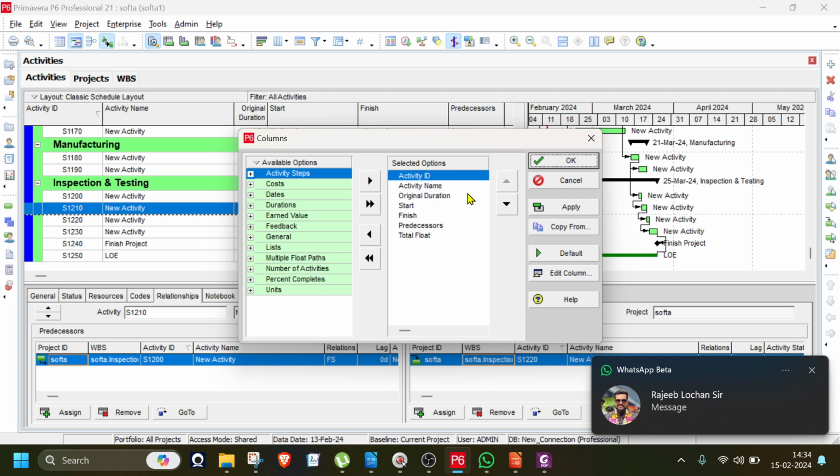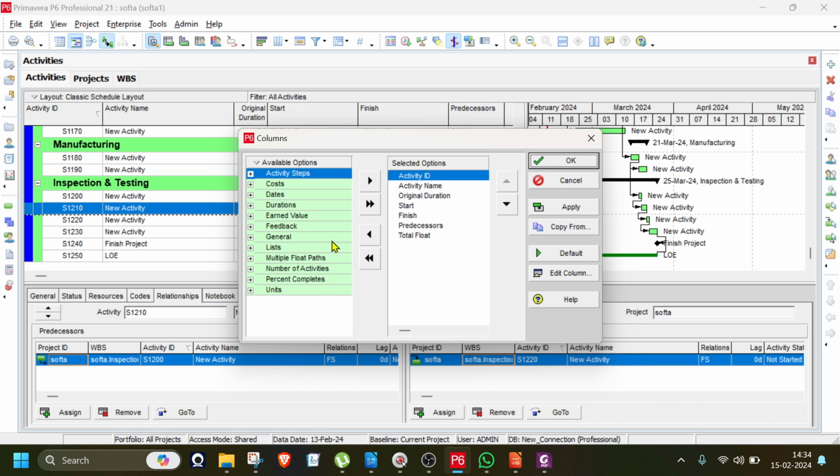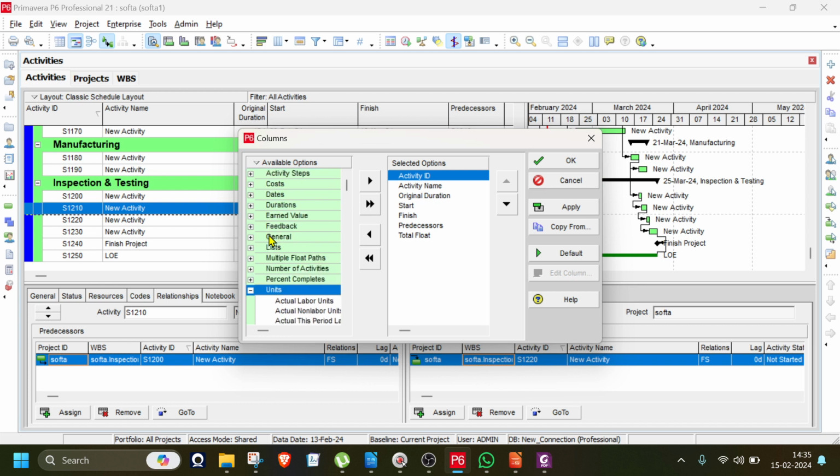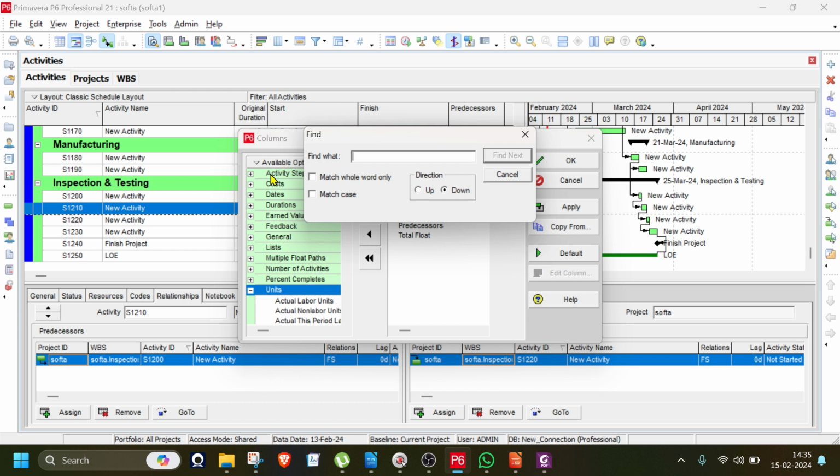See, only one you have to add. We schedule the project using predecessor, right? So successor will come automatically. You don't have to bother about that. If you want to see the successor, bring the successor on the header row. You will get it automatically. Okay, clear? Let me move to the next chapter.